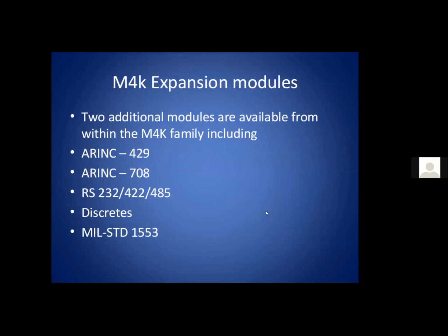Okay, that pretty much covers AFDX. So I'll just talk for a minute about the other modules, because there's room for 2 modules on the card, as we saw. And we've got a whole bunch of different modules, including, but not exclusively, ARINC-429, ARINC-708, serial, discretes, and MIL 1553, which is less likely to be used together with AFDX, which is a civilian spec, whereas MIL 1553 is, of course, a military spec.